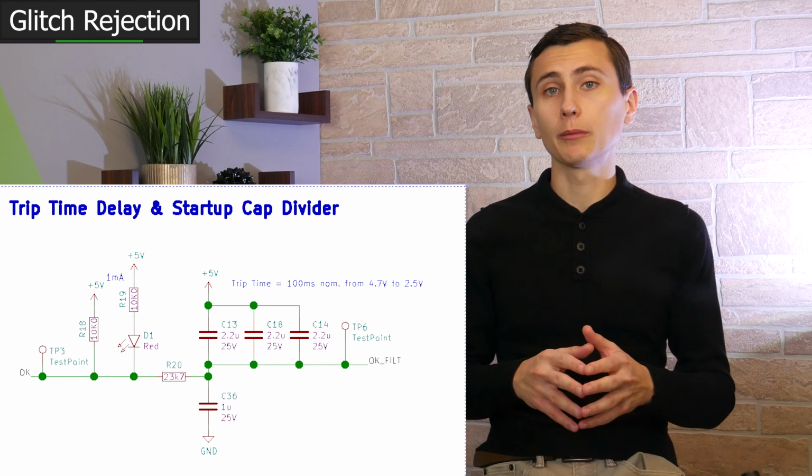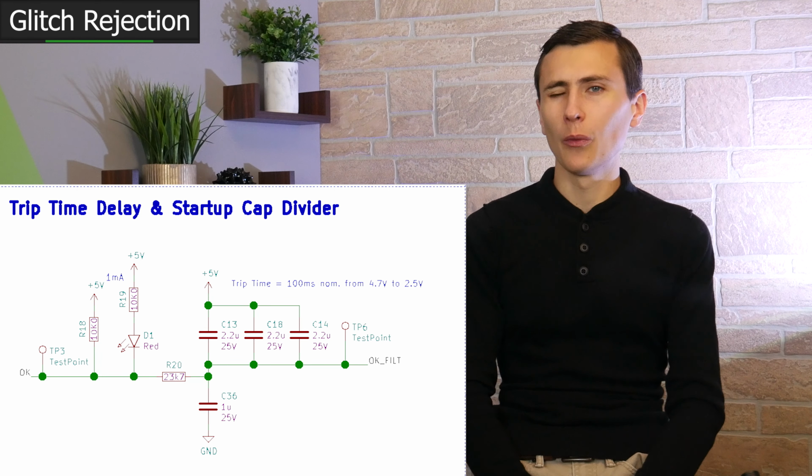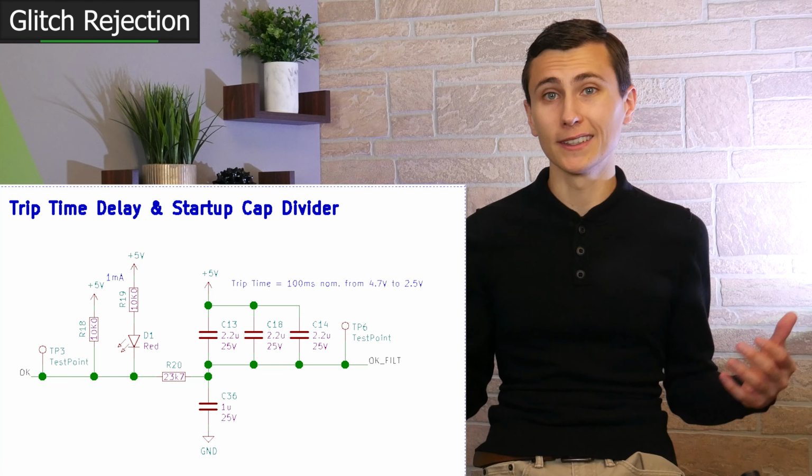Speaking of rubbish, the main opportunity I see for unplanned error in the system is a result of electromagnetic interference or leakage currents. To help mitigate this, if there's some sort of electrical noise causing glitches on the nodes of this circuit, I made sure to add current limiting resistors and a few microfarads of capacitance, which will provide a relatively long time constant. This combination should help to absorb and ride through transient glitches caused by electromagnetic interference without ruining a print and consequently your day.